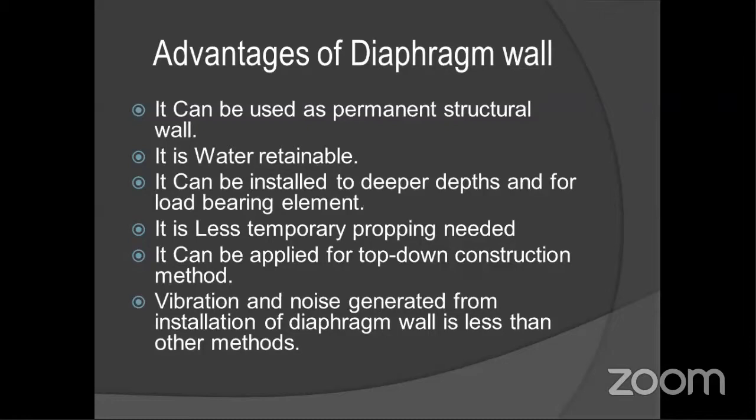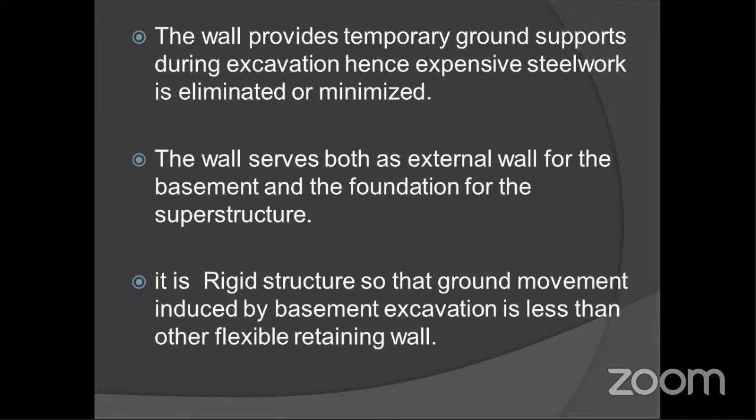In the underground, water will be there, and it will start to come out, so it will delay our process and become costly to prevent all those measures. So for this we go for this type of construction, and it works as the external wall for your structure, and also as the foundation of your superstructure, because we can rest our ground floor slab on it.